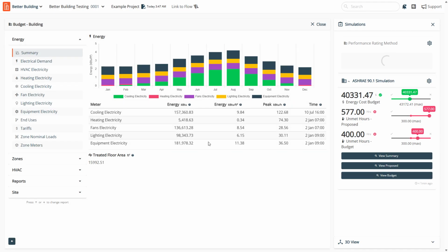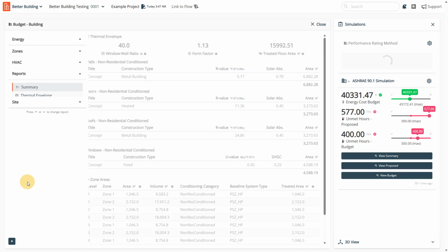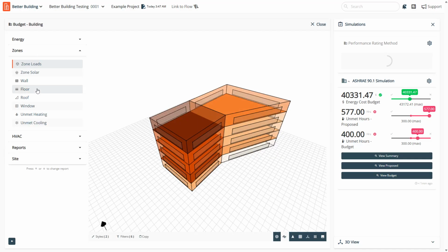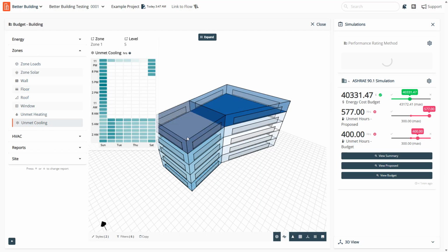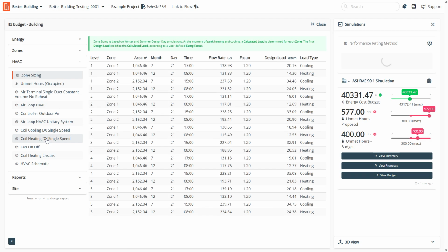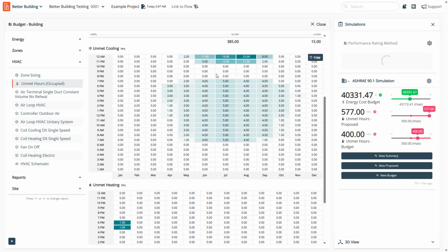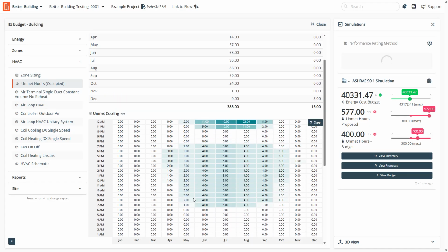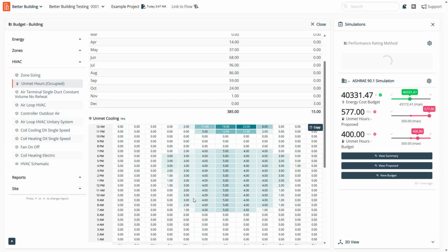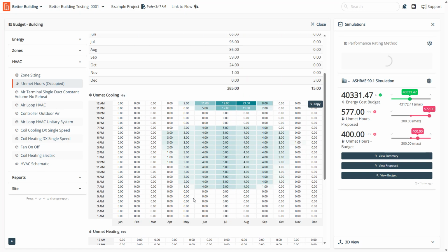I'm just going to pull up this budget building variation that I made there just to identify this change in the total number of unmet hours here. We can see that's now changed in the budget building just because I changed the VRF because of that EnergyPlus OpenStudio error that was coming through. But anyway, hopefully that provides some answer to you, Darius.